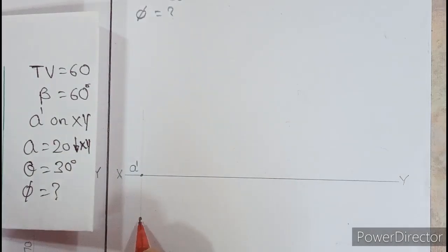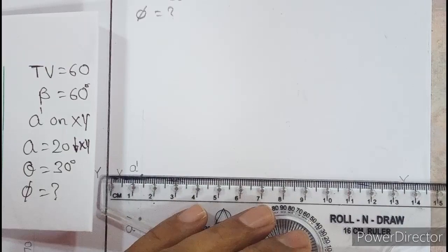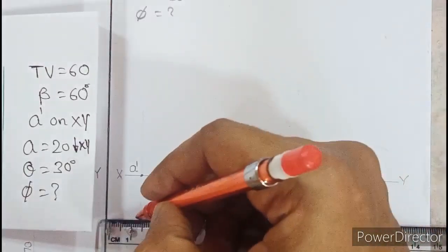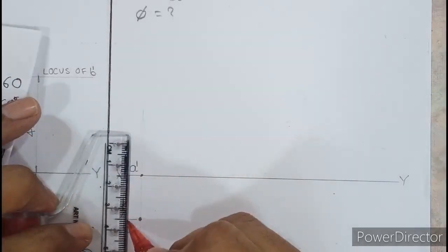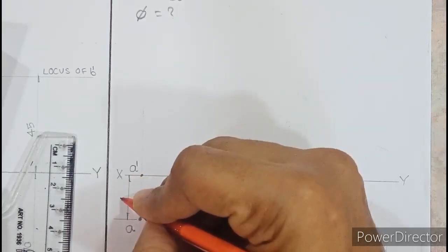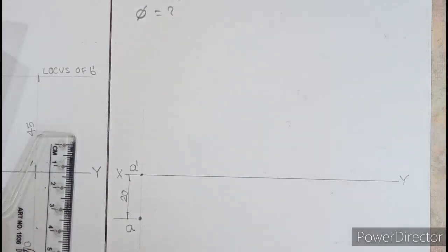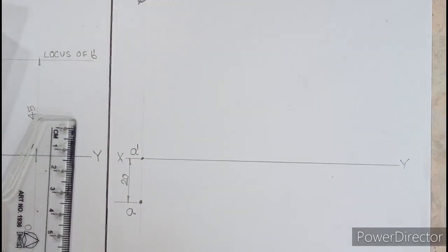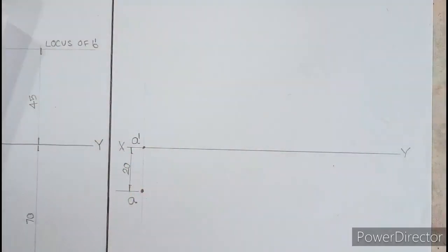So this point you should write where? You should write on the left side and below. So write A neatly here. Next step is dimensioning, don't forget. So from here, roll it down, leave a gap of 2 millimeter, extension line, and from here neatly show dimension 20. So the only fundamental of line is always mark position data first, as you can see here. So you might get 1 mark if the examiner wishes for marking the position data correctly.